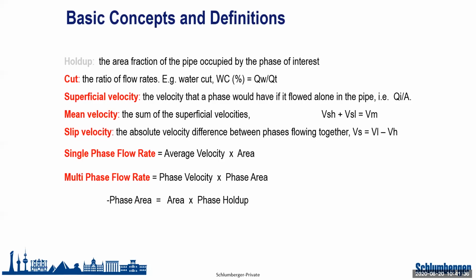Okay? Then, what is the water cut? The water cut is basically a surface measurement. So the water cut is whenever I have my total production at surface, and I see what is the percentage of production of water from the total that I collected at surface. Okay, this is the water cut. So we should never confuse water hold-up with water cut because they are completely different concepts. It is very common that people confuse them, and this will lead to misleading interpretation of the production logs.